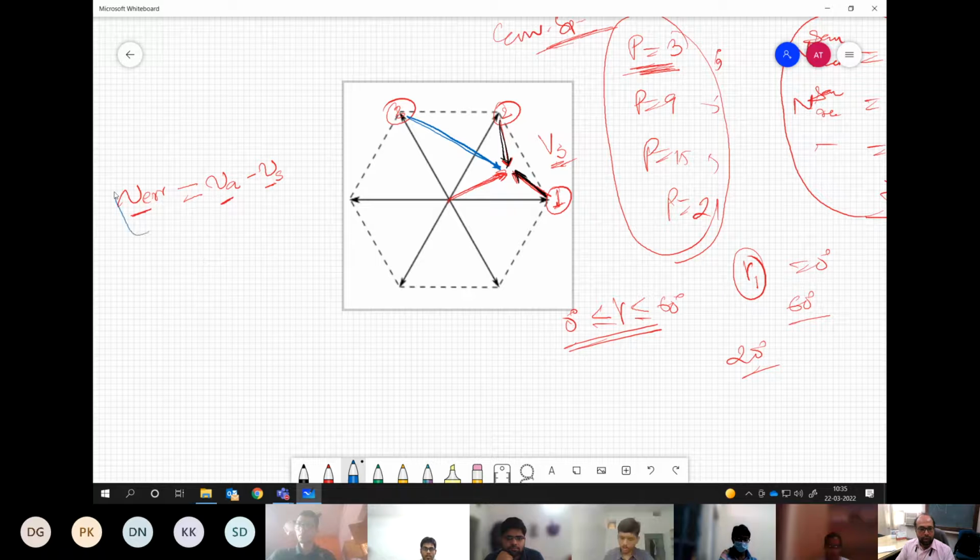So of course we want to have a lower value of voltage error when we are trying to realize it, even on a per phase basis or in a vector form. The ultimate target is to have this voltage error being minimum or reduced. At least keep it low, if not minimized. So certainly 3 is out of question. If we want to keep it minimum, we must use 1 and 2 only for realization of this vector which is falling within this sector.